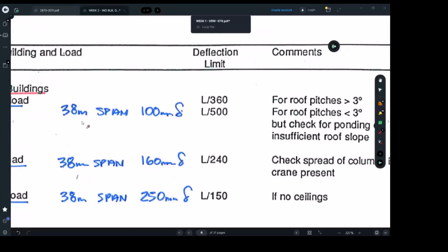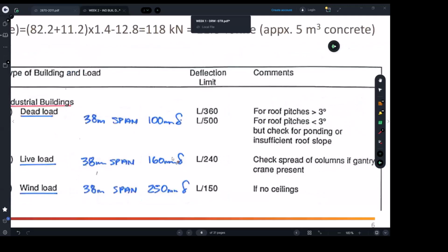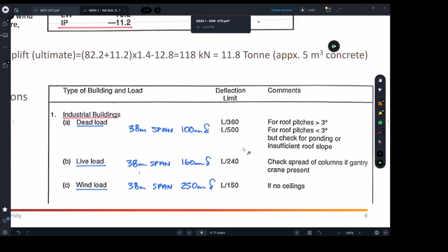You're going to start, if you see you have about 100 mil deflection, that's a problem. 100 mil, it's a lot of deflection. Yeah, it's not acceptable. 40 mil like this is acceptable, and usually there are limits available in many documents for the builders to check with. That's from dead load.